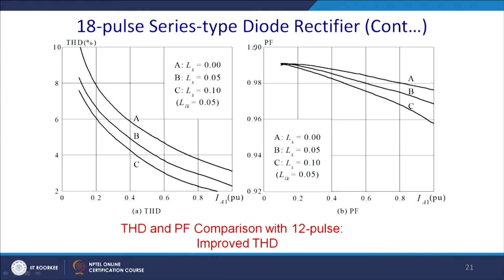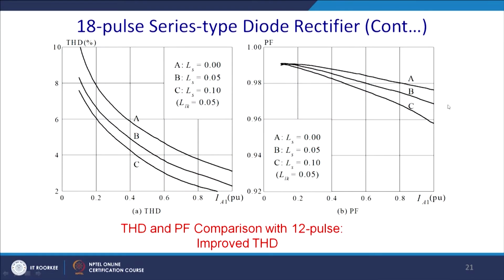Most power quality companies and utilities accept a power factor in and around 0.95. So, they are well in range, and if source inductance is 0, they are well in the range of 0.98. Thus, this should suit all our practical utility purposes for rectification operation.